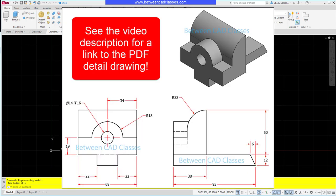Let's take a look at the detailed drawing as I look at my dimensions for my first shape. So once again, I'm going to start with the L-shaped extrusion with the curved surface. I can see that it is 50 millimeters tall and 38 millimeters wide. From the front view, I can see that the front portion is 19 millimeters tall. And based upon the 22 millimeter radius here, I can see that the top portion is 22 millimeters thick. Finally, from the front view, I can see that this shape is going to be extruded 68 millimeters.